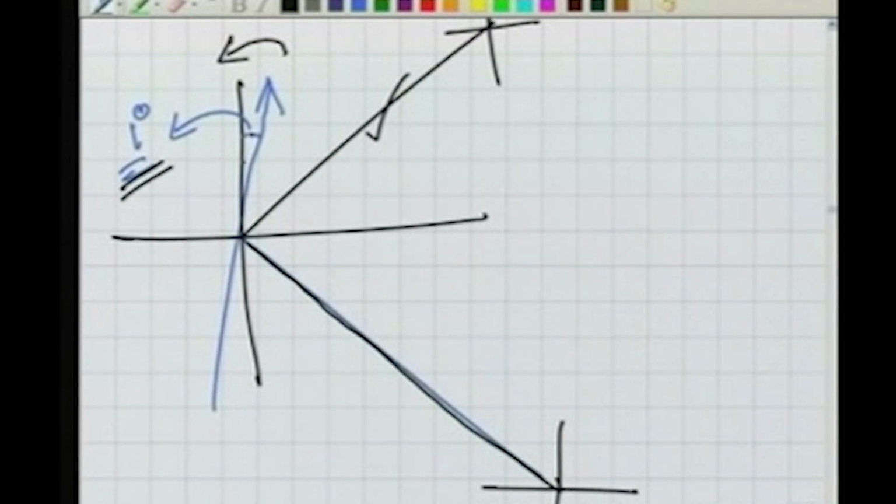So whatever was the bearing observed for this line, because that will be the value. If I delete this small one here, because in actual practice what we are doing is observing the bearing from this line. The magnetic needle is pointing in this direction because of the local attraction. So we are taking observations, the bearing of this line from here. So for this bearing also, we need to apply the correction as we had done for this line, because we know at this point the correction is in this direction by this amount.